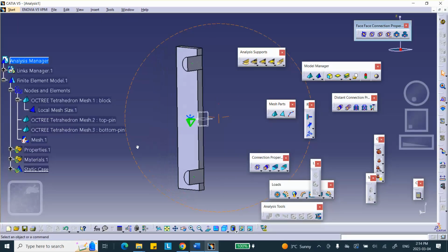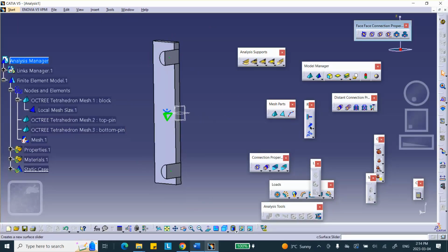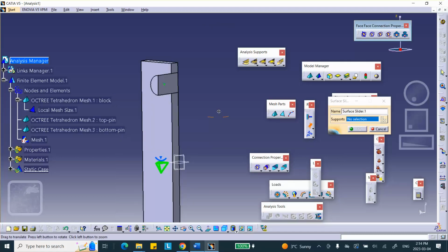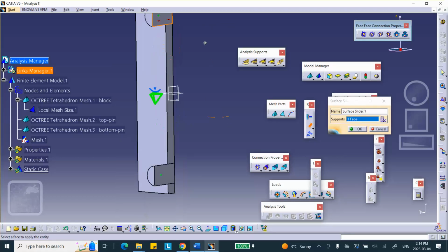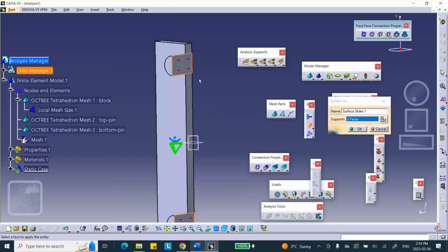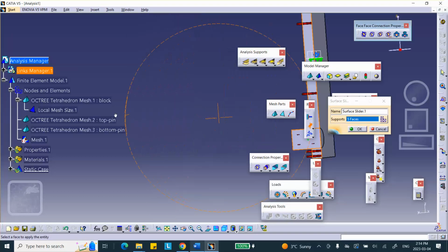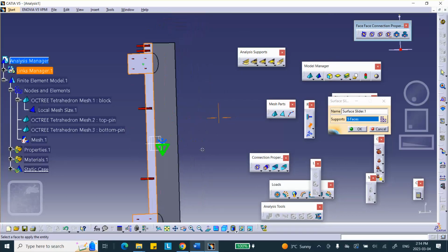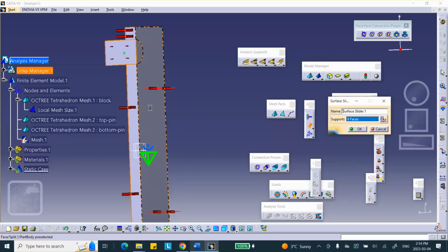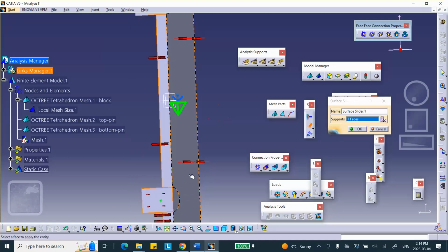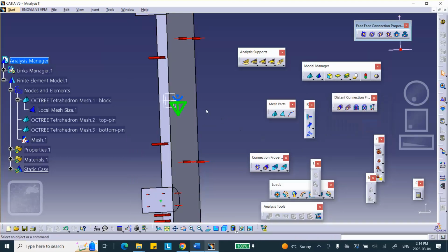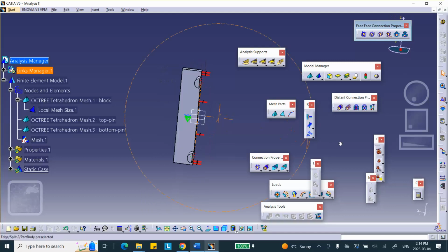Now, surface sliders. Anything that you cut and is a plane of symmetry is a surface slider. So this is a surface slider. This is a surface slider. This top piece is a surface slider. And here and here. If you want to do them all at the same time, you might as well do this face, side face, this half a quarter, half a circle, and that half a circle. These are all planes of symmetry. They were introduced because of the cuts that we made.